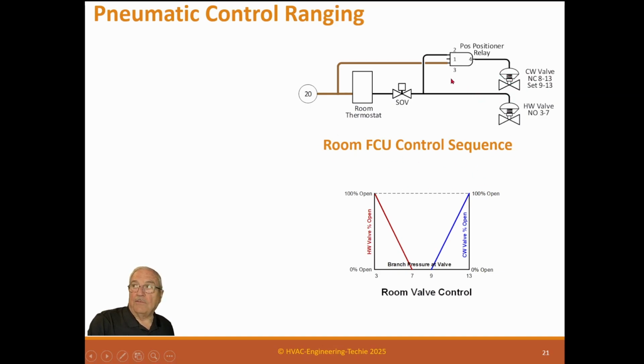You also have relays in there that will allow this to have more air, because you see you got air coming right into this device. So this will make this actuator quicker, because it's actually giving more air than this thermostat. The thermostat's a pretty limiting device, but you can put a relay up here that has a much larger orifice in it, and it'll move this up and down much quicker. So that's the one way to do it.